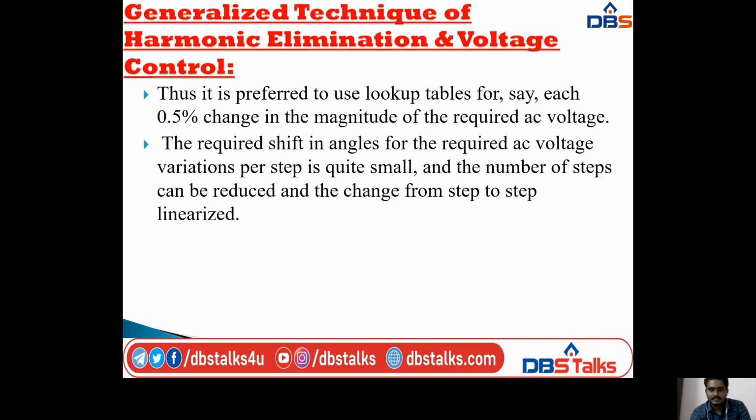Thus it is preferred to use lookup tables for, say, each 0.5% change in the magnitude of the required AC voltage.